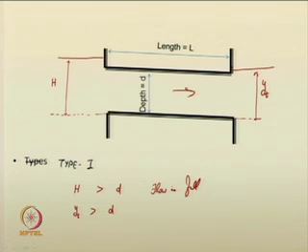So, this is type 1, it is more like a pipe flow. Here you cannot apply the open channel principles to find the type of flow inside the culvert, because it is a constriction, all around it is bounded. So, it is more like a pipe flow, you have to use the pipe flow principles.